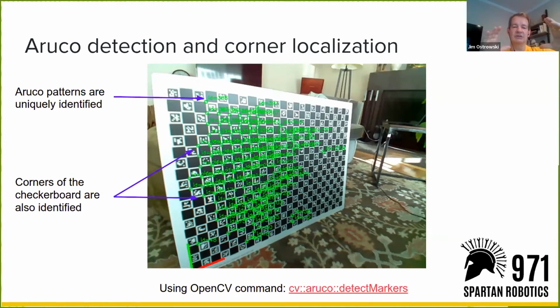So you want to make sure you're getting sample points all around the lens, because at the end of the day, what we're going to be doing is trying to understand the distortions and the camera center based on knowing where these points are relative to each other, and mapping what the camera intrinsics have done to distort where those points are relative to where they should be in the ideal world. That's how we're going to figure out the camera intrinsics.